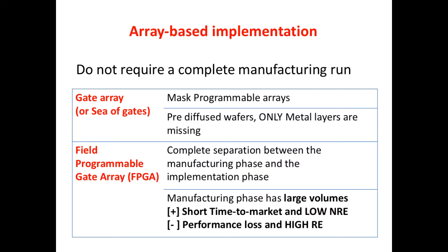And the other case is when you need to do some fast prototyping of a chip. So you can do the first prototype, first generation. It's almost a pilot production with an FPGA. If everything works and then you want to go to large volumes, you substitute the FPGA with a semi-custom chip, because in this case at least you have lower costs per item.